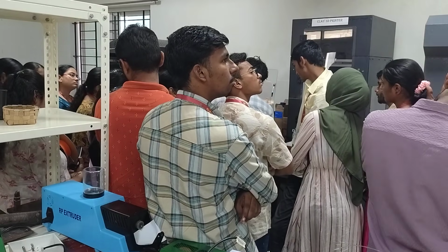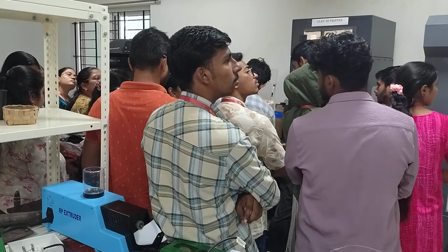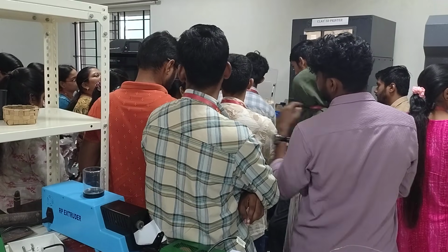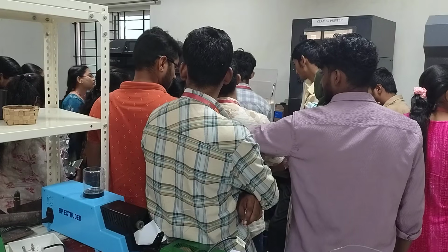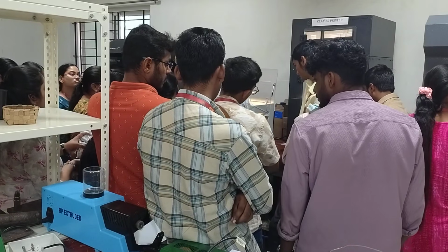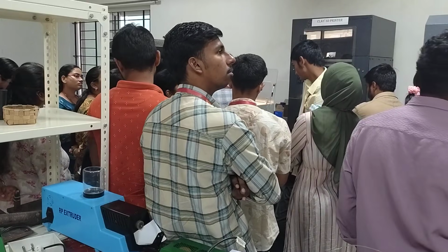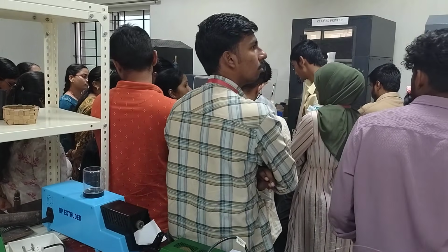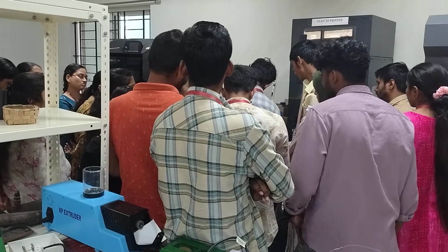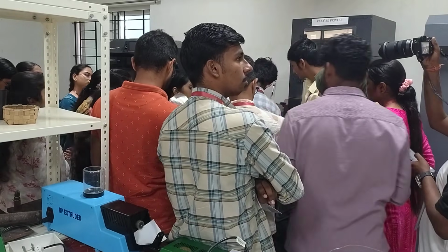So now it is telling something. "Clear the leftover filament from the extruder if necessary. When finished, press next." From the extruder, if there is a leftover filament, I have already removed it, then I'll click on next. Now it's telling, "Put the plastic into the filament feed tube. Until the extruder is loaded, wait for the plastic to feed through the tube. When the plastic starts coming out of the nozzle, press stop."